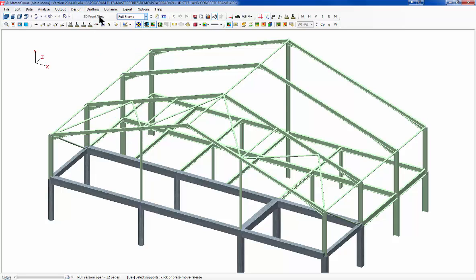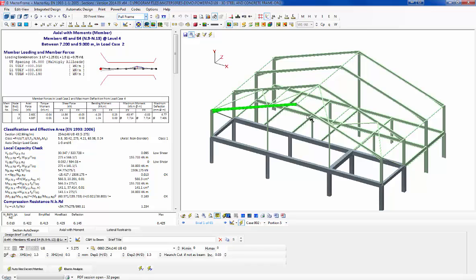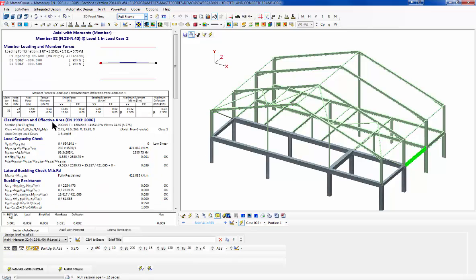We can integrate it, come straight through into the design. And I can take any particular member, one of these wee trimming members, and I can see to the Eurocode that it was a compound section, the plate girder, and it's actually working fine. It's actually very under stress because the load has not been applied to it. Look at this member, it's fine.